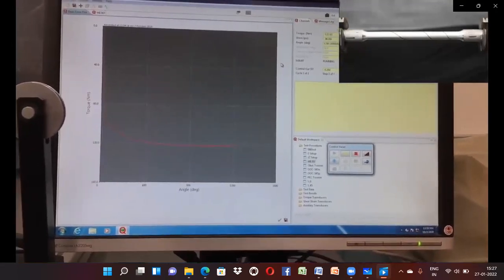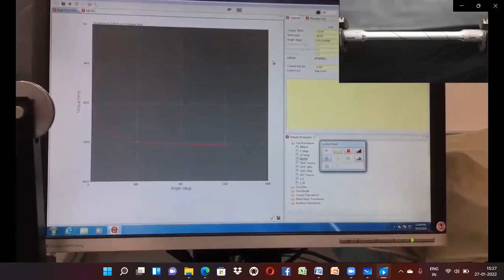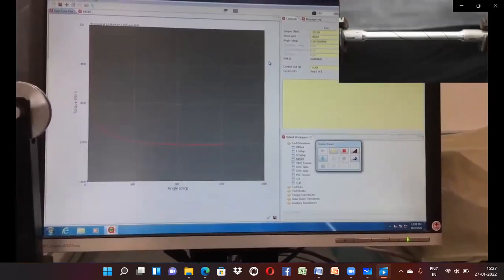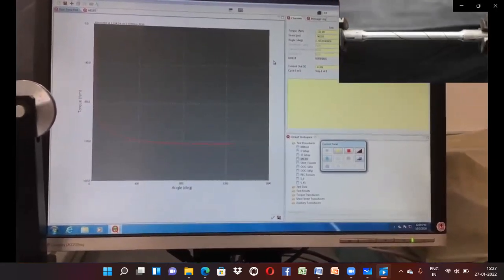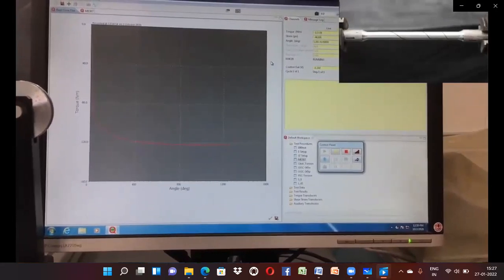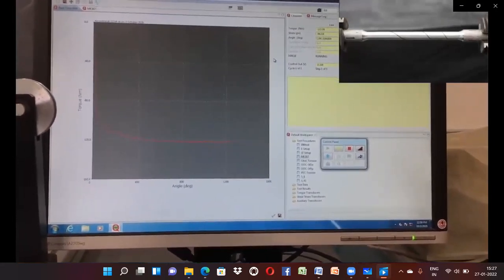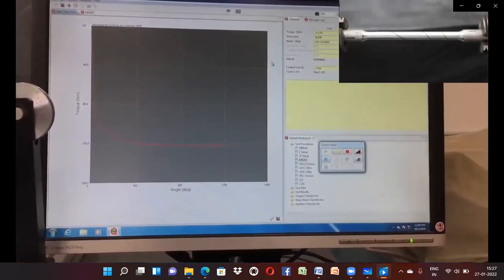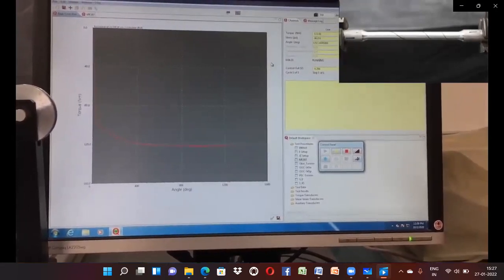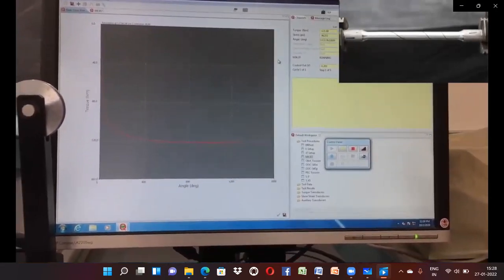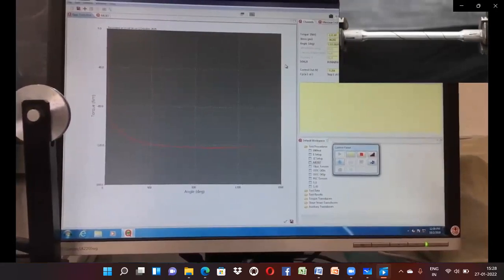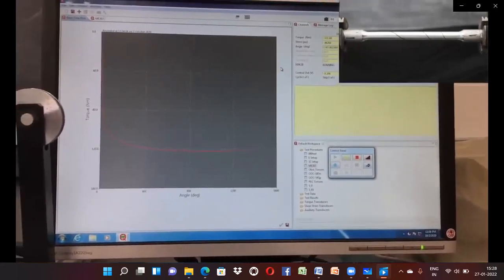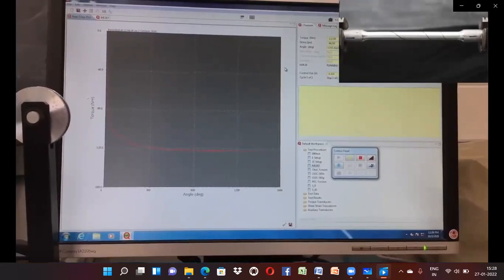Why is that? There might be some cracks forming. There might be some locations on the surface where we have achieved the ultimate shear stress, and it's beginning to fail. And so if I were a betting man, which I'm not, I would bet that it's going to fail on the right end, just because that's where all the deformation is starting to happen.